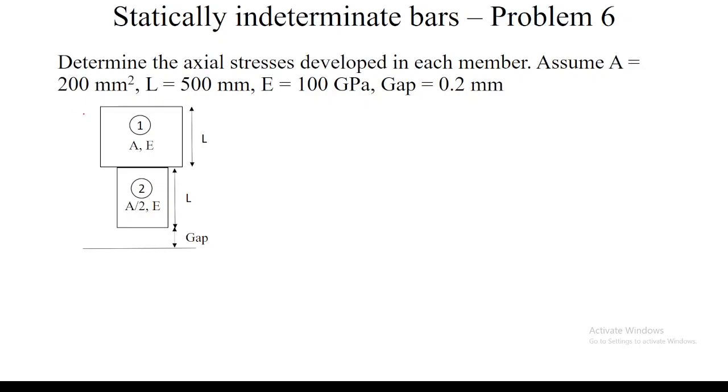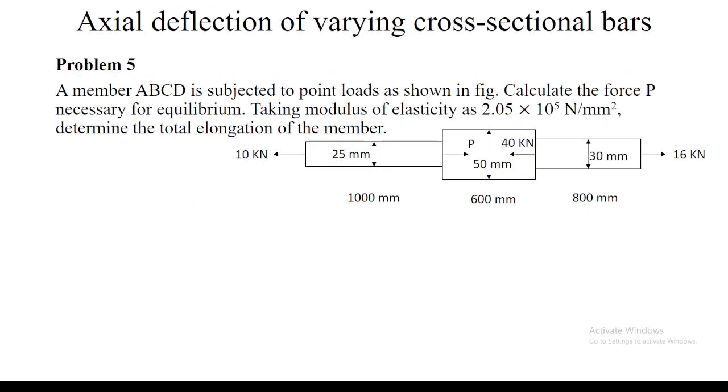Statically determinate means that, based on the force balance, I can find the value of the externally applied loads or the reactions of the supports. Whereas for statically indeterminate bars, I can't find the reactions explicitly. Is what I told you clear? Can you repeat once? Yes, for example, in this previous example, this is a statically determinate member.